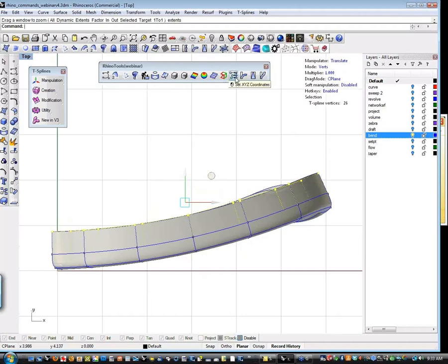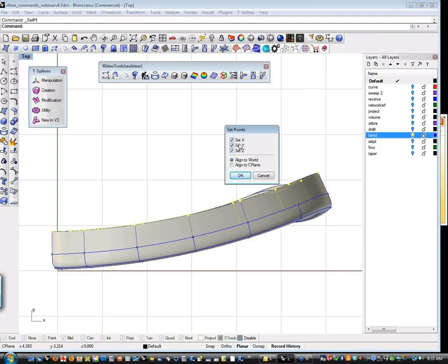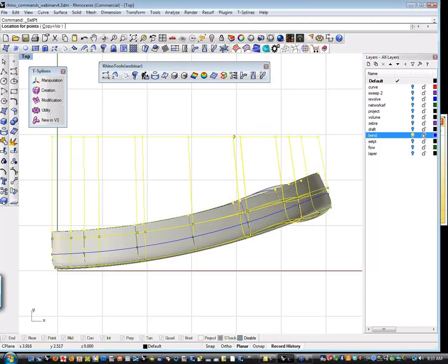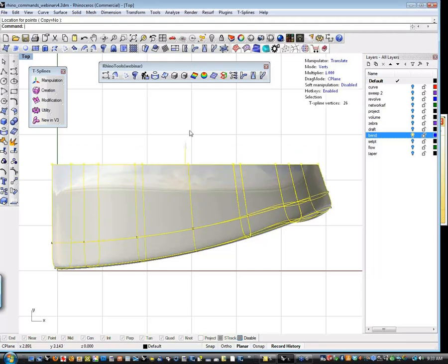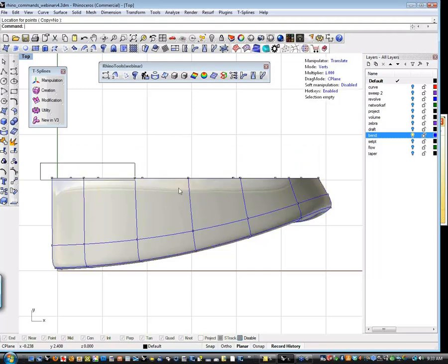And I built a little button here. So if you hit that, it's going to bring up your XYZ coordinates, and in this case I want to set them to the Y, and so I'm going to shut off everything except for the Y and say go, and you'll notice that those points line up like little airplanes coming into JFK, and then you can just pick the spot where you want them to go. Once they're lined up, you can move them, or for that case, if you want to get really slick, you can bend them again